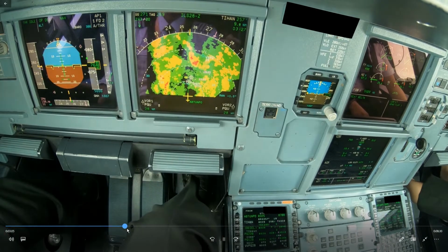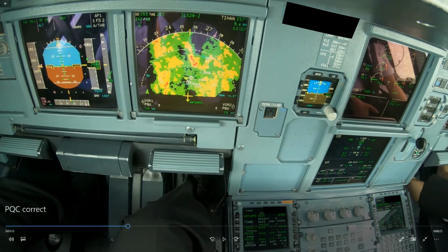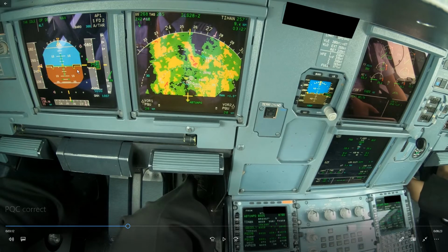Here is 30 miles exactly, and we are 500 feet high. Again, we check the weight and the wind. We have a bit more headwind now. So 500 feet high at 30 miles is maybe not a problem. We could use the speed brake to get back on profile, but at the moment it looks like perhaps there's no need for that. So we can just wait and see.